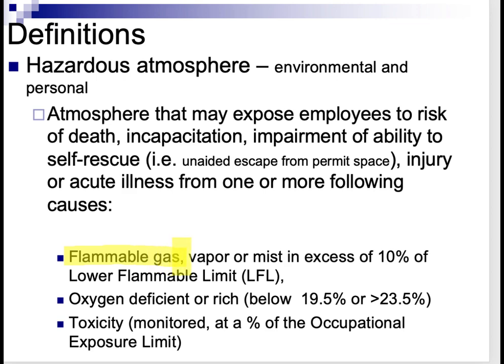And we set our alarm, so our lowest measurement, at 10% of the lower flammability limit of some gas that we choose. And it's very important to make that distinction that not all gases will alarm at this setting. It's only the gas that we set our meter to.